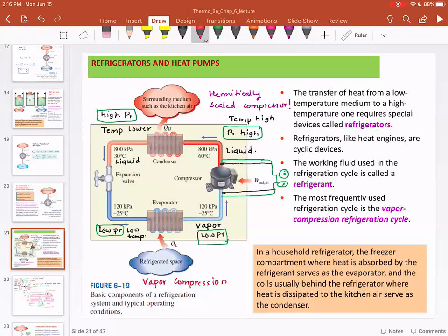So you have compressed air available to you free of cost when you are flying an aircraft. In that case, they take this compressed air, cool it down, and throttle it through an expansion valve, and then it is expanded in the cabin.